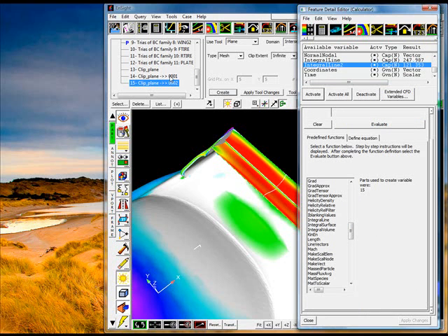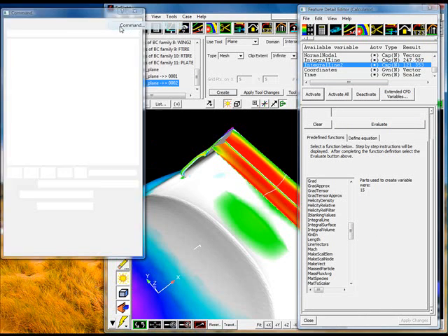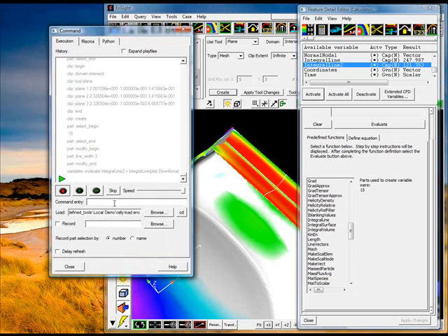So again, we select this entity with this section cut and go back to our command again and issue our test special 2D plot, the distance over which we'd like to go, and the number of values. And now it's moving this section cut, generating and integrating this value and storing it in a query.